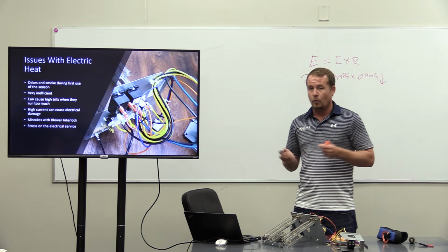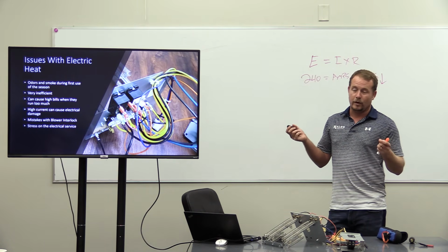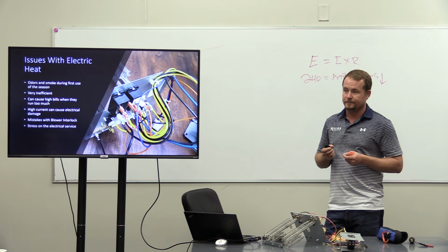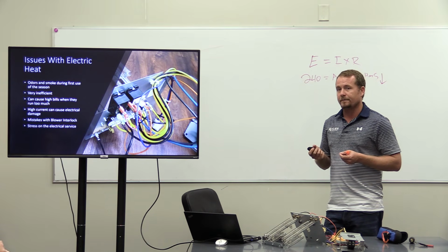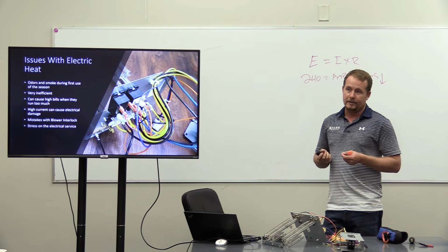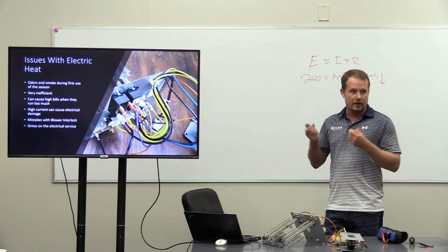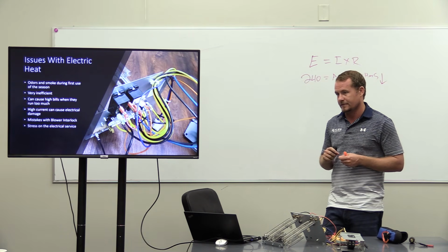Why do we need the blower to run when the heat strips are on? Potential fire hazard, right? They get very hot. And if they keep cycling on and off, on and off, on and off, and something gets in there, it could potentially cause a fire.